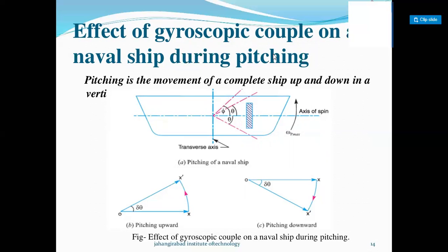In the figure, the angle theta shown is the angular displacement of the ship axis from its mean equilibrium position, where capital A denotes the amplitude of swing, equal to the angle in degrees times 2 pi divided by 360, right? Where omega 0 is the angular velocity of the simple harmonic motion, taken as 2 pi divided by the time period, right? So the angular motion is given as theta equals A sine omega 0 t.